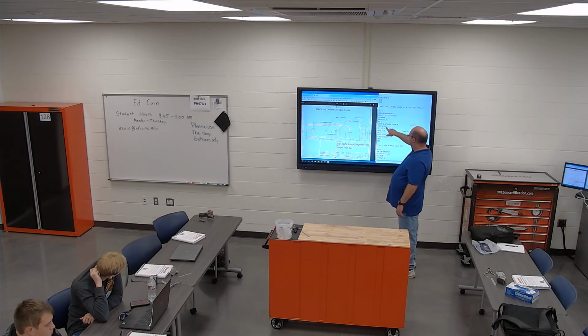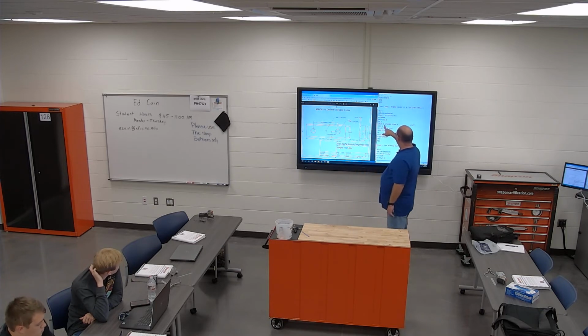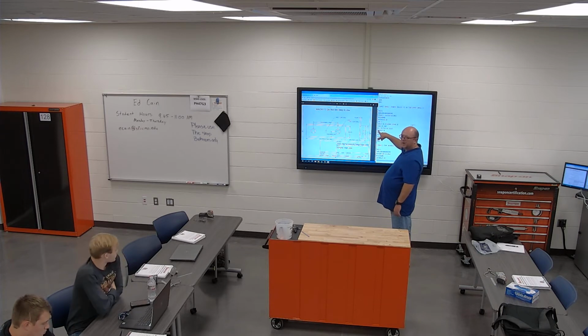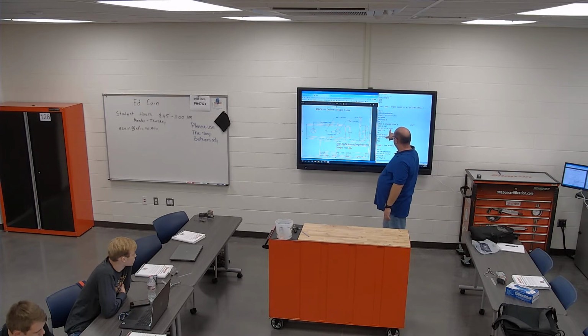X0 Z of 0.187, which is what this figures out to be with the chamfer that I left on it. So if you're not changing the height of your chamfer or the width of your chamfer, you don't have to put the Z. You can just do X and Y's. And then the second one I did X of opposite the one up here, positive 1.9375, and then the Z of negative, so it matches the same as this hole.